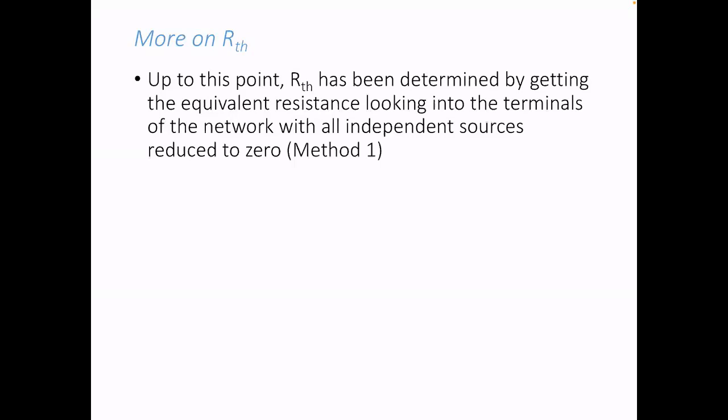Okay, so in our discussion last Tuesday, the way we determined the Thevenin resistance was we got the equivalent resistance looking into the terminals of the network with all independent sources reduced to 0.